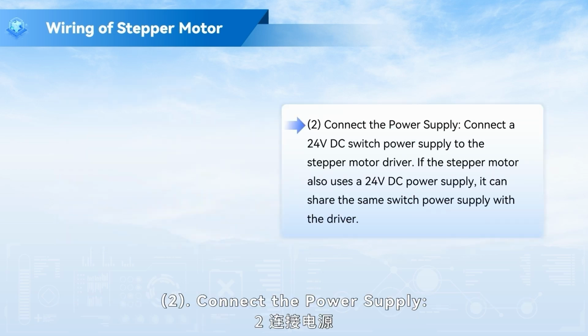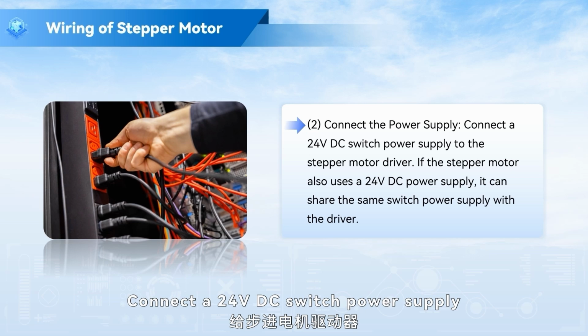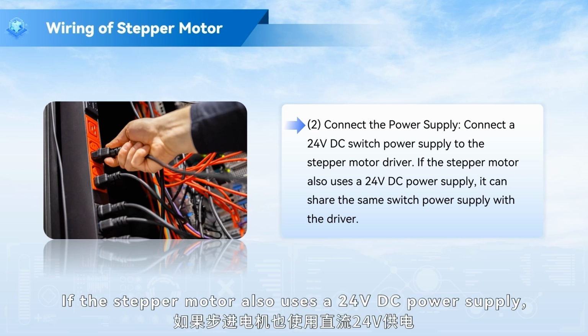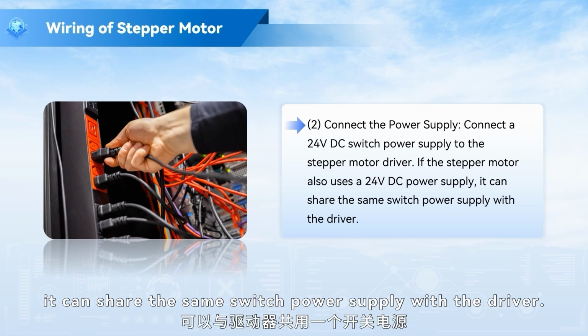2. Connect the power supply. Connect a 24 volts DC switch power supply to the stepper motor driver. If the stepper motor also uses a 24 volts DC power supply, it can share the same switch power supply with the driver.